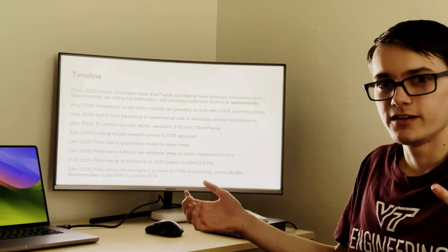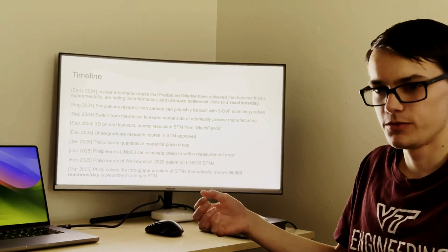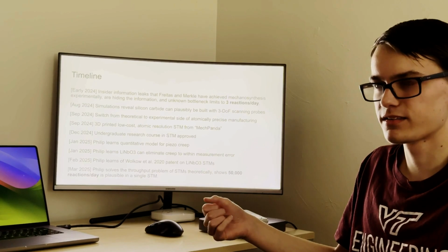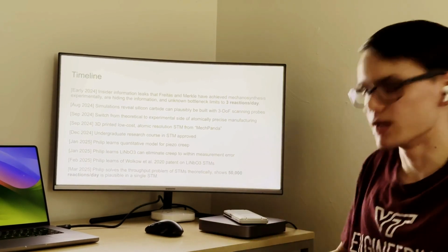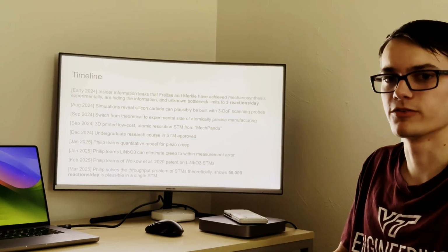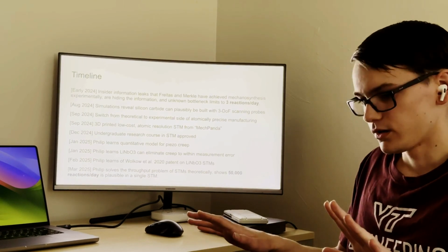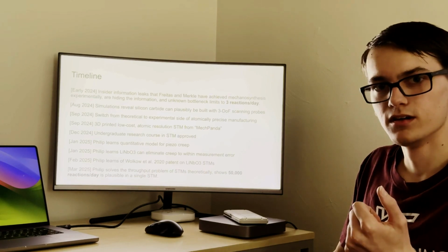Well, apparently you can't. You need at least ultra high vacuum. You can't do it with a diffusion pump, which gets like 10 to the negative 8 torr at best. You need to have a turbo pump. That's the bare minimum of cost, which is several thousands of dollars, to build any atoms that'll stick to a non-oxidized surface.